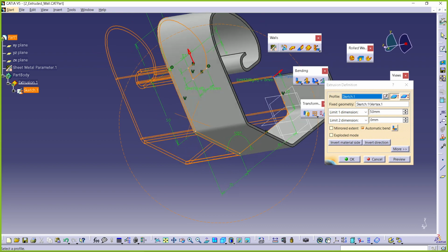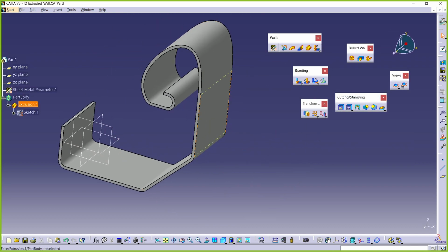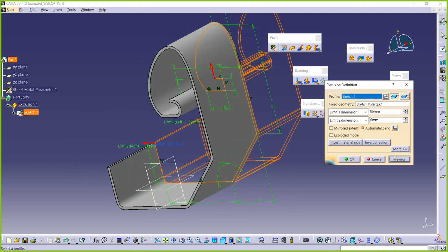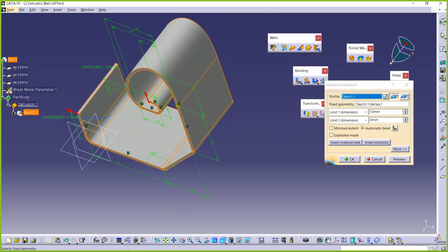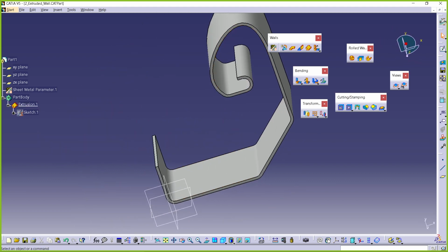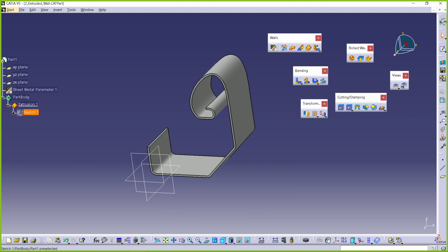means you can change the direction. You can change the direction here, like reverse direction in part design. Similarly, this feature is available here also. Now here there is sketch extreme position and sketch middle position, which I will explain in the wall. When I go for the wall, we can go with this. Again here, the blend is not required because the k factor always takes the default. Okay, this is how, if you have an open profile, that time you can go with